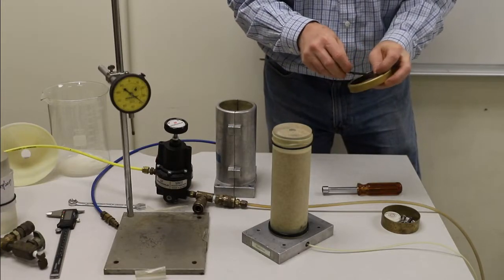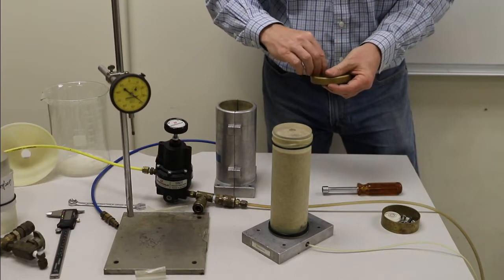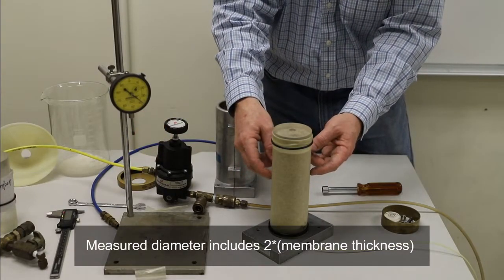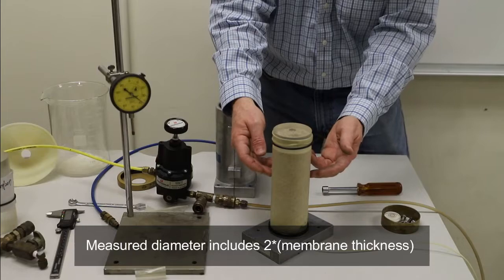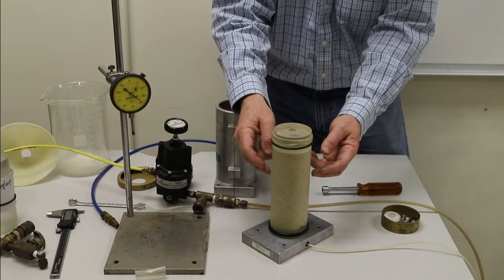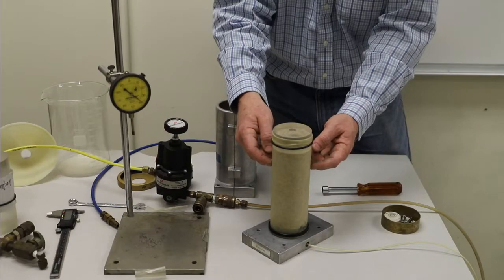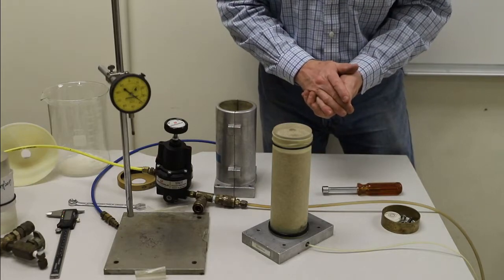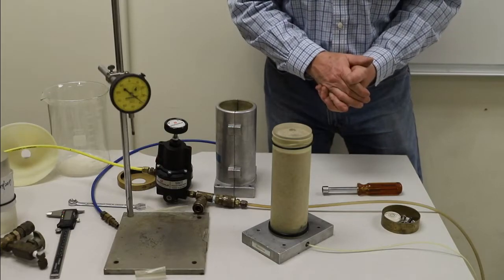What diameter is that we've just measured? It's the diameter of the specimen, but it's on the outside of the membrane. The membrane is not sand. So really what we want is the diameter of the sand specimen. So remember at the beginning we measured the thickness of the membrane. So we want to take our calculated diameter and subtract 2 times the thickness in order to get the diameter of the sand itself. So that's what goes into measuring the initial cross-sectional area and the initial volume when you multiply it by the initial height.